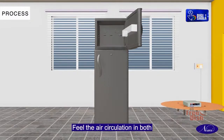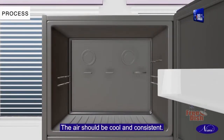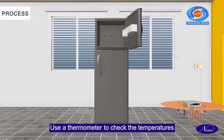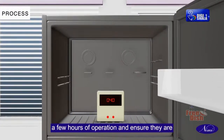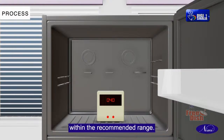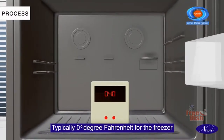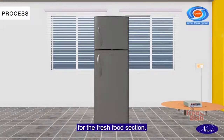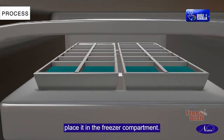Feel the air circulation in both the freezer and fresh food compartments. The air should be cool and consistent. Use a thermometer to check the temperatures in different compartments after a few hours of operation and ensure they are within the recommended range. Typically 0 degrees Fahrenheit for the freezer and around 37 to 40 degrees Fahrenheit for the fresh food section. Fill the ice tray with water and place it in the freezer compartment.